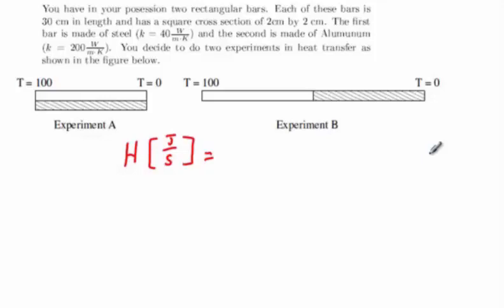What we find is that if the heat is transferred by conduction through a solid, liquid, or gas, we have a parameterized formula that tells us that the heat flow is equal to the thermal conductivity times a few geometrical factors. The heat flow is largest with a big area, and it decreases as the length of the bar increases. And finally, the heat flow is related to the difference in temperature between the two ends. This formula will be applied in both experiment A and in experiment B.